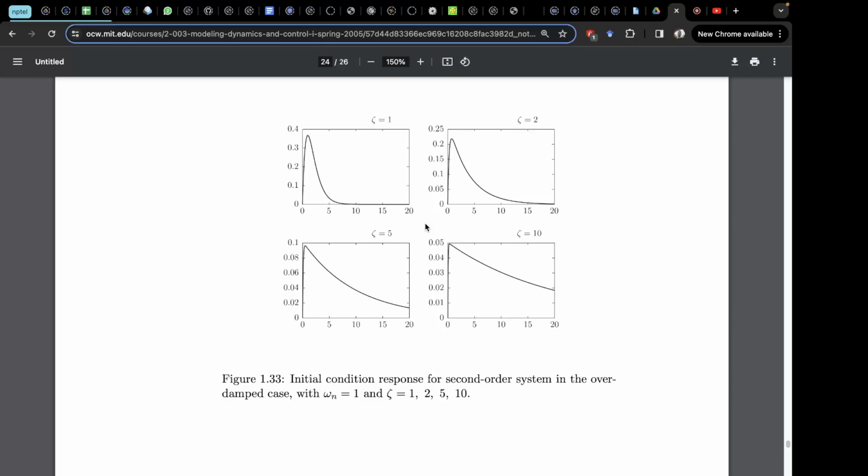If you just use a single cubic polynomial between 0 and 10 seconds, a cubic polynomial has 4 parameters that can be set. As we saw in the trajectory generation discussion hour, by defining the velocity and the position at both the endpoints, we can uniquely identify the 4 parameters of the cubic.